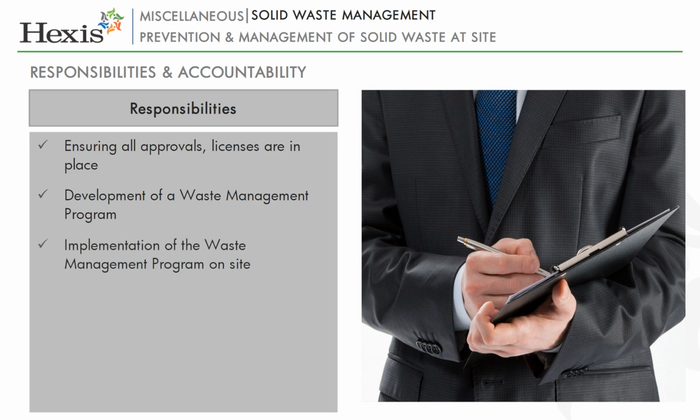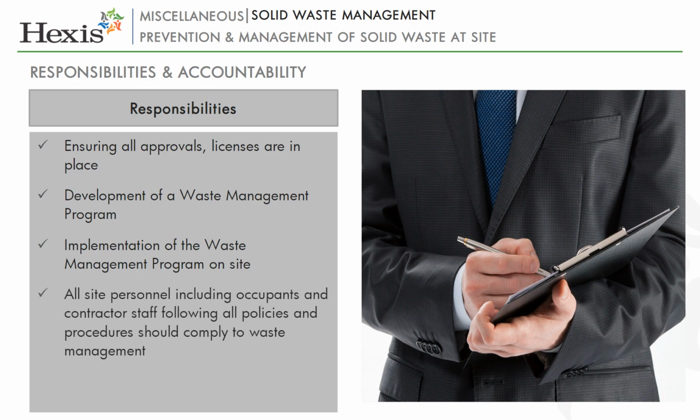Implementation of the waste management program on site, with adequate resources for the waste prevention and management to be provided. Ensure the vendors involved in collection, handling, storage, disposal, etc. are also aware of the program requirements. All site personnel including occupants and contractor staff should follow all policies and procedures to ensure compliance with waste management. Develop educational material for on-site management. This could be training modules, posters, signage, labeling, etc. Staff should be encouraged to report all concerns regarding the waste like leaks, spills, etc.